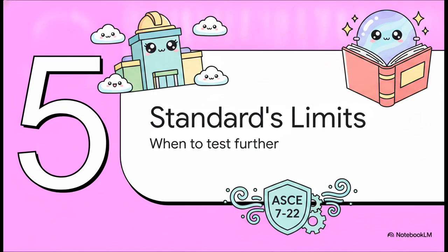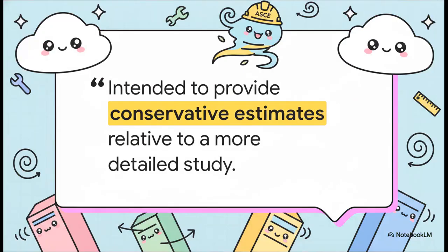Finally, Part 5. Knowing the standard's limits, because keeping buildings safe means recognizing that a code book is not a crystal ball. Expertly using ASCE 7-22 means understanding exactly what it cannot do. As the authors explicitly state, this standard is ultimately a simplified analytical tool. Developing it involved trade-offs. The pressure coefficients are enveloping, meaning they capture the highest peak values regardless of wind direction, which realistically won't all happen simultaneously on a structure. It's highly conservative, yes, but it inherently lacks the nuance for estimating complex crosswind and torsional excitations on wild architectures.